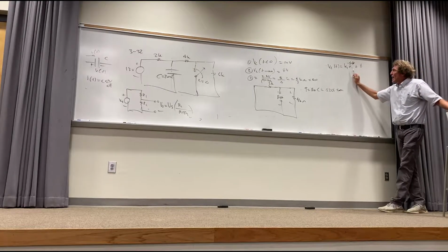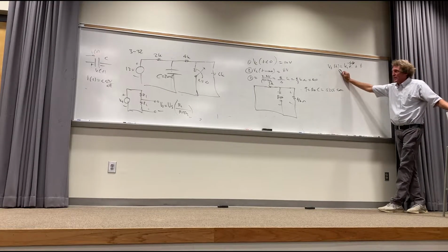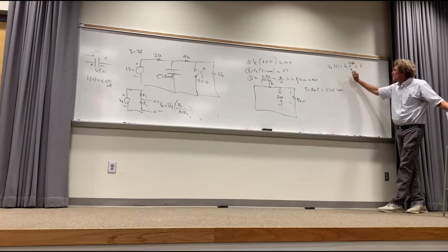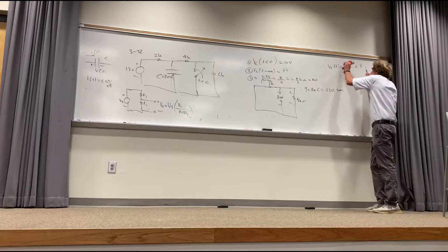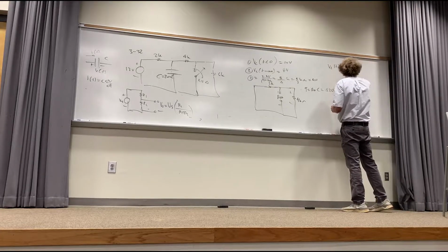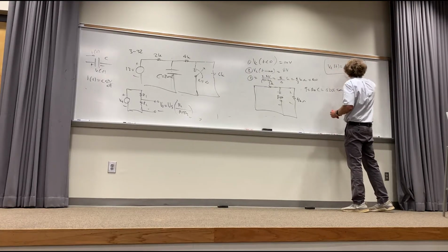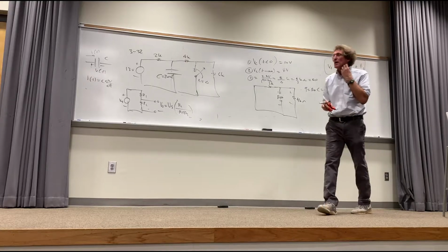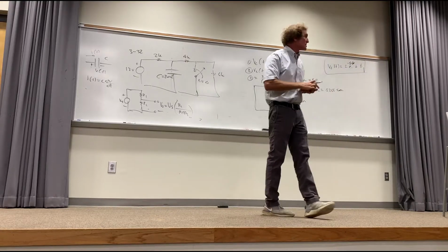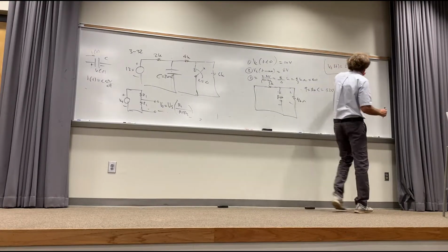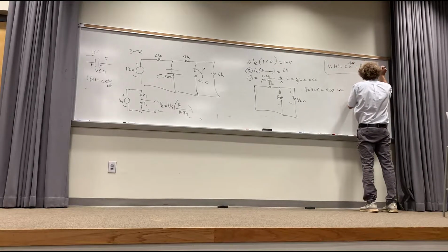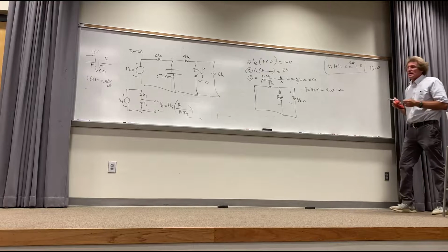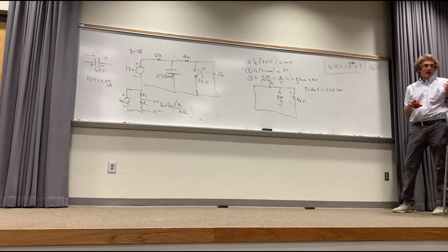All right, so at 0, this is 10, isn't it? 10 equals K1 plus 8. So K1 is 2. Now you have the general equation for voltage across the capacitor for t greater than 0. You'll have to put this one stipulation. I'm not harsh on you for that. But this is for t greater than or equal to 0. It starts at 10, decays to 8. Everybody with me? And it stays at 8.